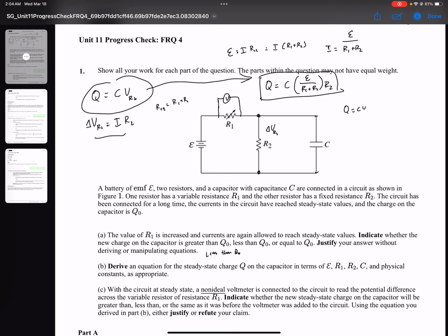Okay? So if you're probing circuit elements that also have very, very large resistances, and you're probing very, very tiny circuits that have very small amounts of current going through them, then you have to consider that with your voltmeter. In other words, if the voltmeter has a large but not infinite resistance, then it is in parallel with this resistor R1.